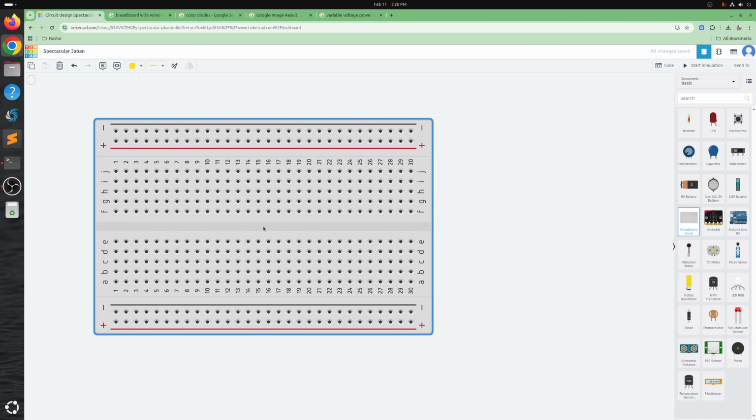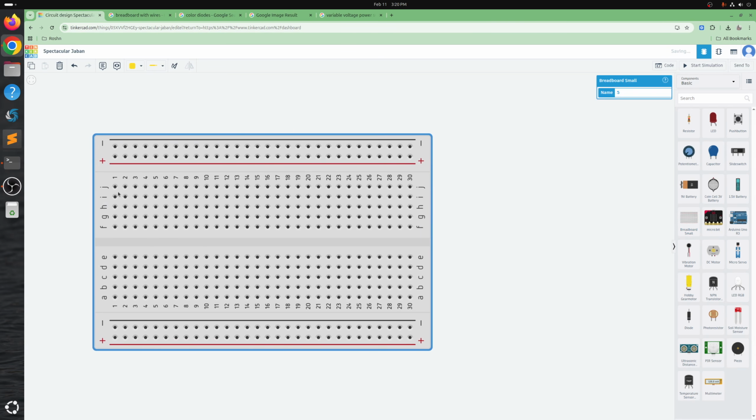So we'll just go ahead and design this simple circuit. We'll use the breadboard first. In the breadboard you may see there are rows and there are columns. The rows are interconnected, as you can see, with the green bubbles. Whenever you are connecting any diode or anything, you should always connect it between two different columns. If you connect it within the same row, that means you are not creating any voltage difference, so essentially the circuit won't be formed. It won't be a working circuit. So you have to connect it between two different columns.